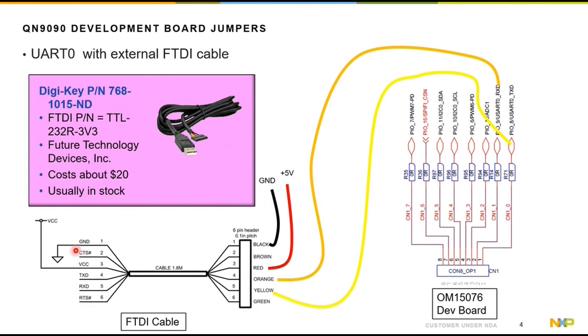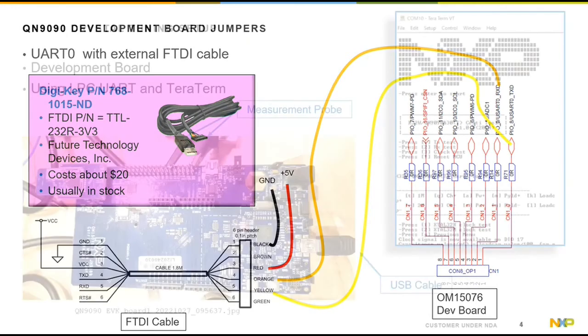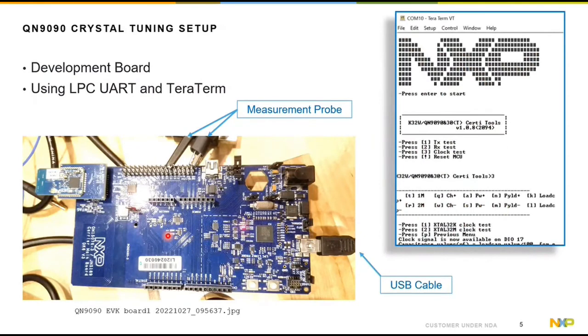And the cable powers itself. So molded in this case is an IC, and that's powered off your 5 volts coming off of your USB side of your computer. And so our boards have an FTDI connection on here, or you could jump around to this connector here, which is what I showed on the previous slide, and use an FTDI cable overmolded with the IC inside of it.